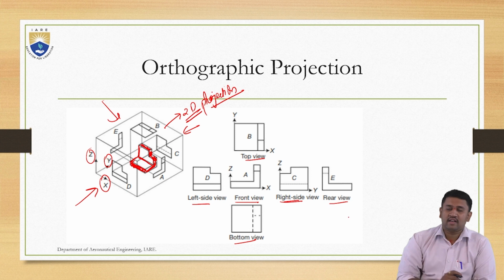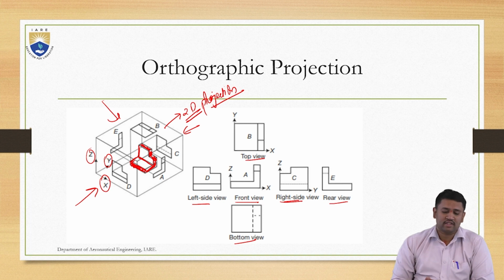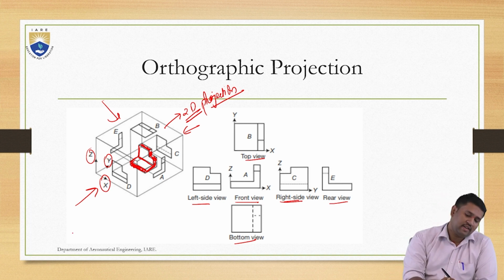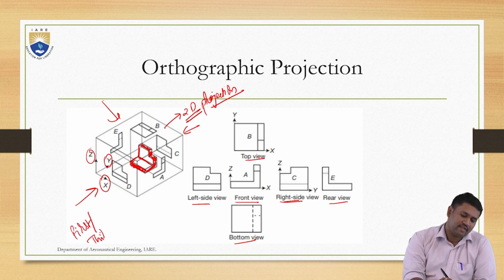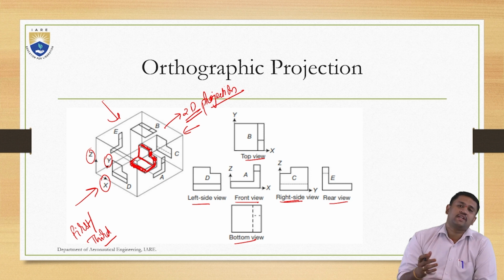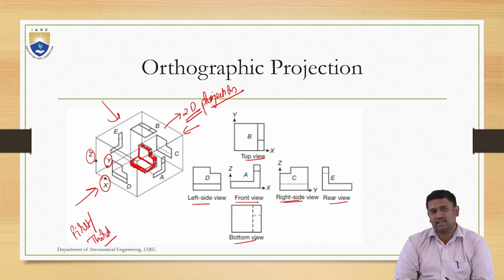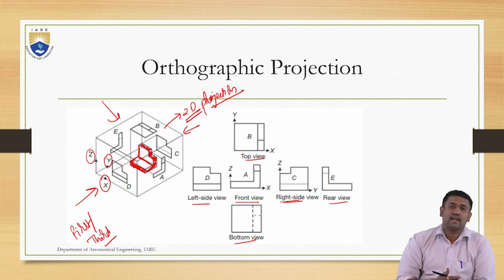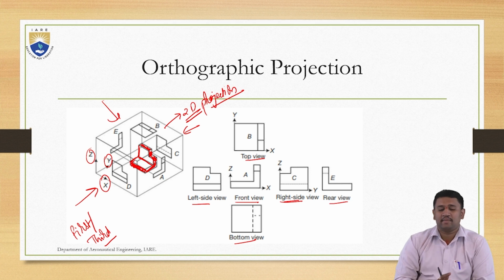These are all the 6 sides of your cube, right? These are your 6 basic views under orthogonal projection. Depending on the type of projection, particularly first angle or third angle, which basically means putting your object in the first quadrant or third quadrant, you get a series of views that are necessary to completely understand an image.